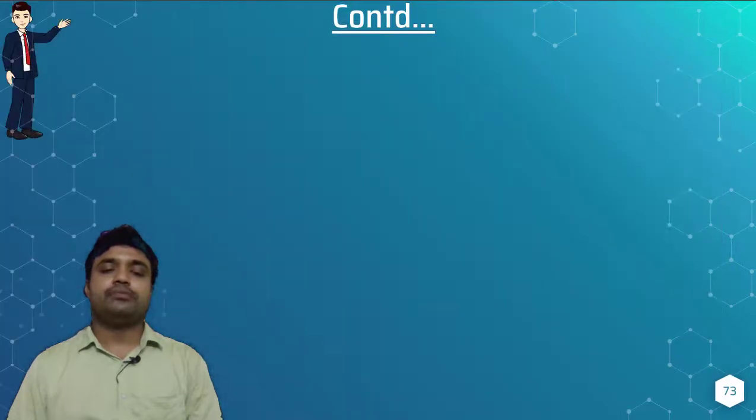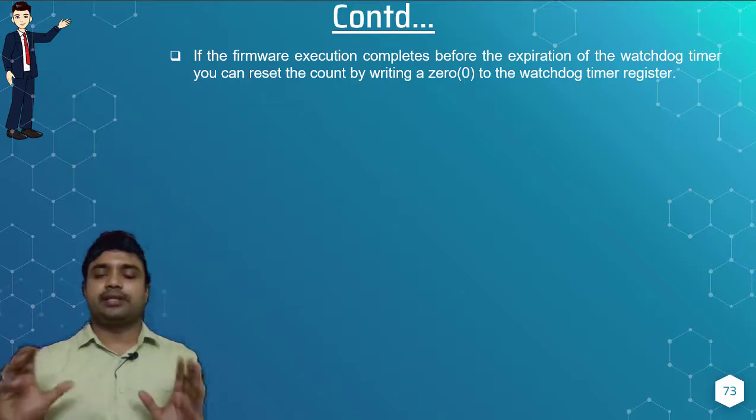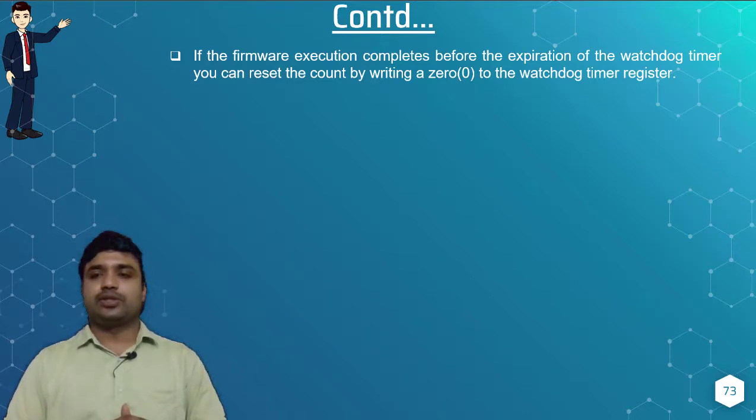Okay, and next, if the firmware execution completes before the expiration of the watchdog timer, a reset operation can be performed by writing a 0 to the watchdog timer register. If the firmware execution completes before the expiration, that means within the specified time interval, if the work is done, it is considered to be a good thing. But for the watchdog timer, there is an exceptional case.